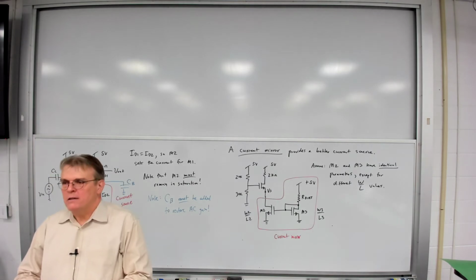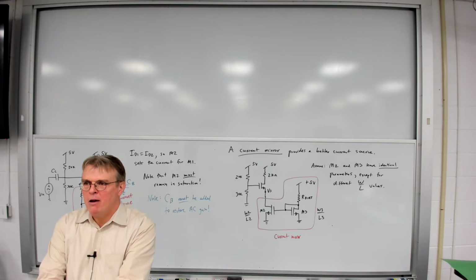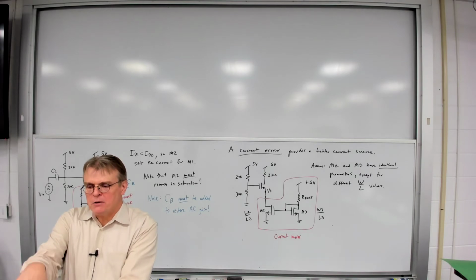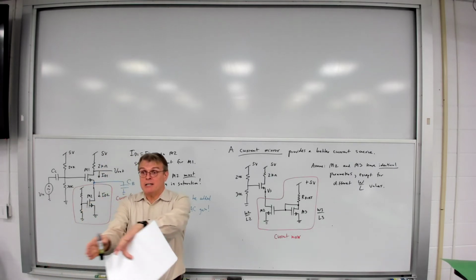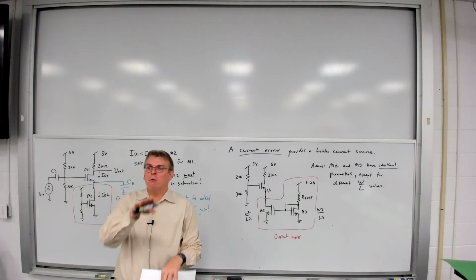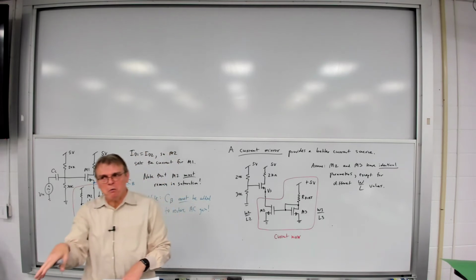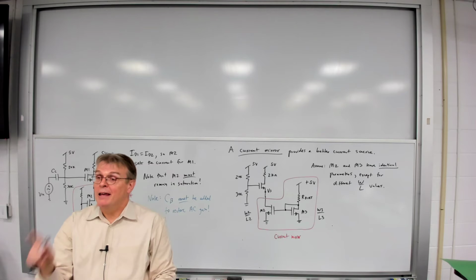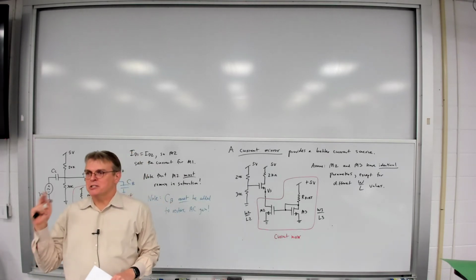And that is to make sure that we manufacture them both at the same time, on the same die, under the same manufacturing conditions, and we put them right next to each other. So whatever one transistor is exposed to during the manufacturing process, the other one is also exposed to. If you do that, then you have what you call two matched devices.